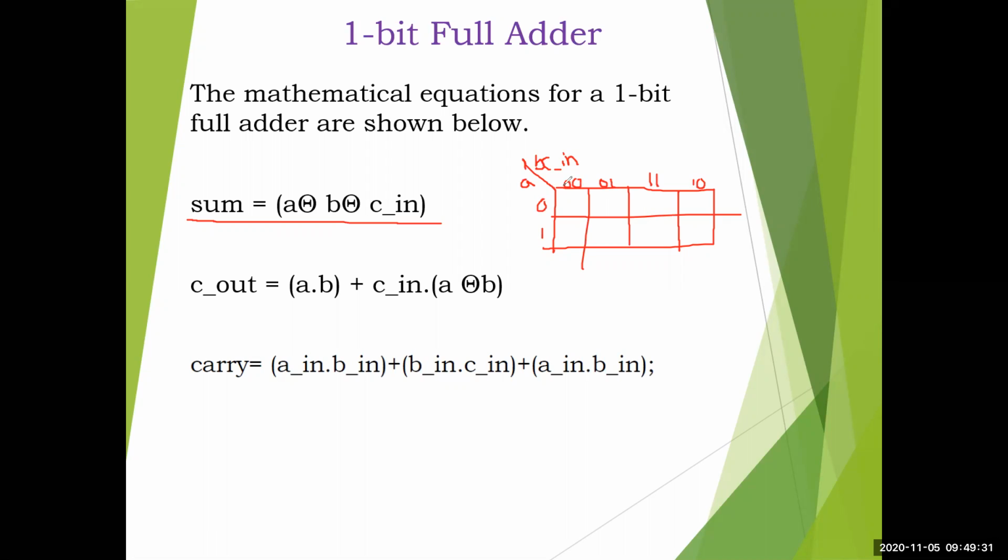So why is this? Because from 000 to this, only 1 bit is changed here. So 1 is already there, and this 0 is changed to 1 now. Next, 11 is there, so just 1 bit is changed. Every time there is a 1 bit transition. Now if you enter the output there: 000 gives 0, 001 gives 1, 011 gives 0, 010 gives 1, next 100 gives 1, 101 gives 0, 111 gives 1. Okay, so in this case, even if you make the K-map also, you'll get the same, right?